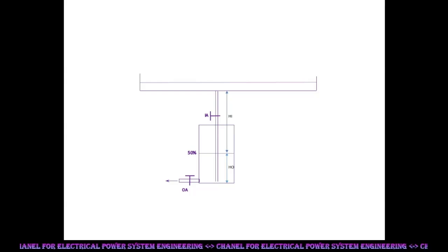Power draw increases when consumers start more load. The system frequency starts dropping due to shortage of power. The governor system increases input to the power plant with the speed drop, so power injection increases automatically. Similarly, load demand decreases with dropping frequency on account of frequency sensitive loads. Both these corrections continue till power injection and draw are balanced. Frequency is again steady at a slightly lower level.